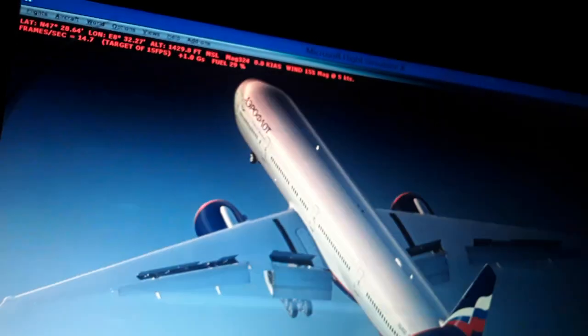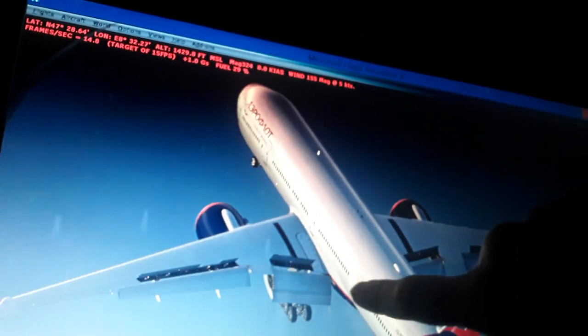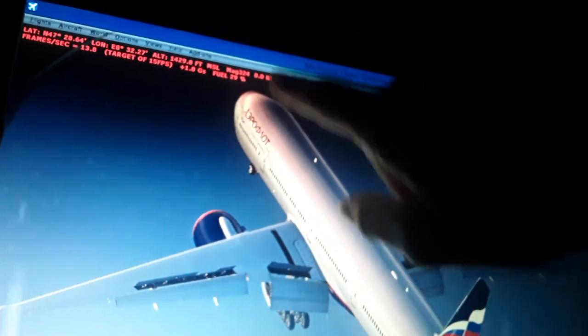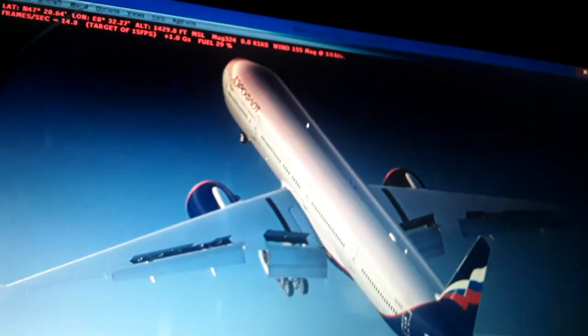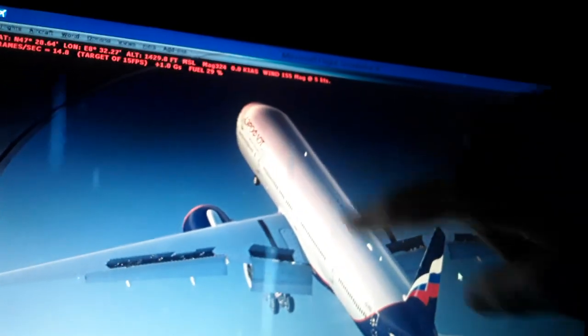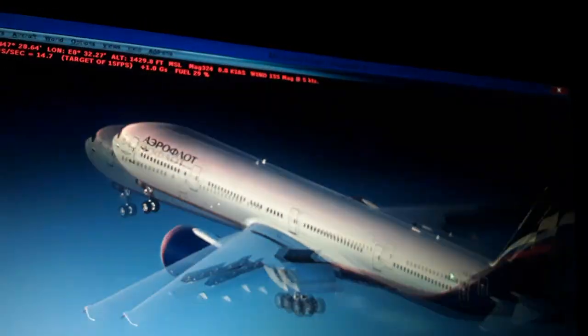It's also the position where the center of gravity is, where the vectors of the horizontal, longitudinal, lateral (wingtip to wingtip), and vertical axes are traversed through the center of gravity of the aircraft. You can shift the center of gravity of the aircraft forward or aft by shifting fuel, passengers and cargo, making it less or more stable.